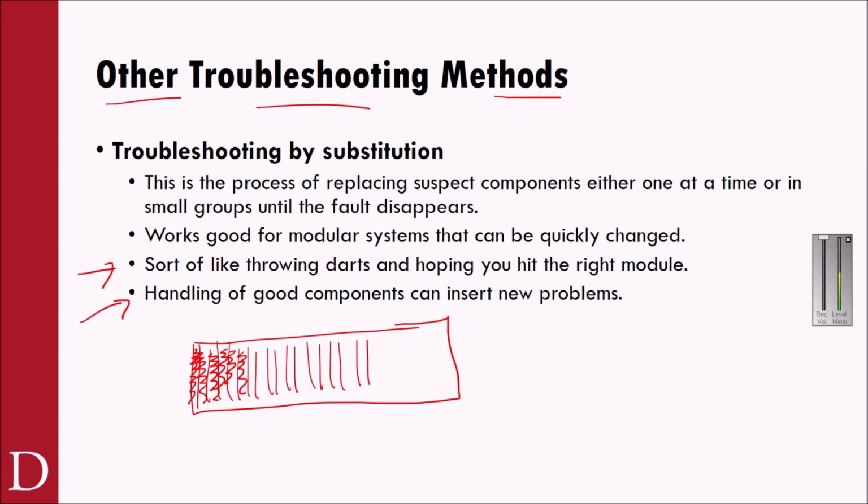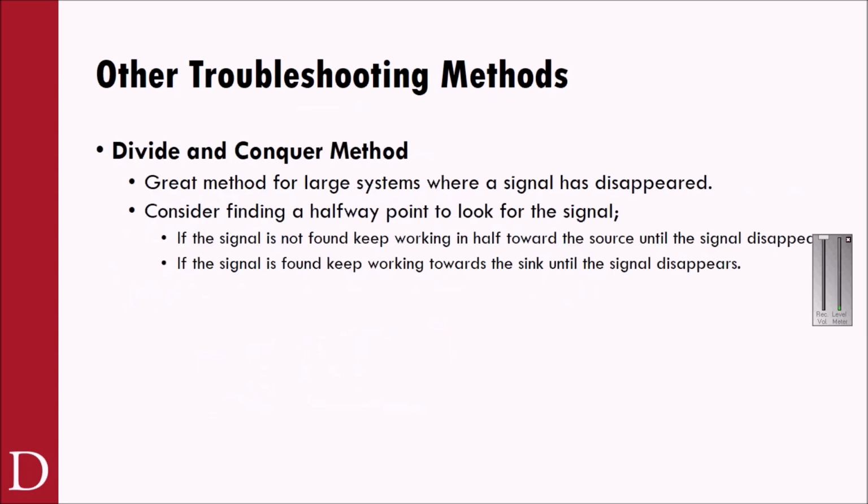The other thing I don't like about this one is I don't like the idea of yanking out good components and then putting them back in. So I pull 3 components out, put in 3 good spares, find out that the good spares didn't change anything. Do I take those good spares out and replace them back with my original components? Well, now if these components have connectors on them, wires on them, you only get a certain amount of times that you can plug a module in and out before you're actually going to insert other problems into the system.